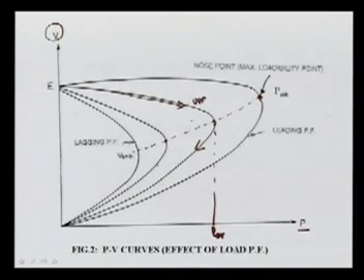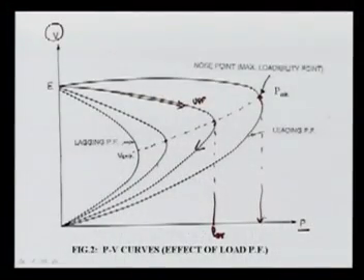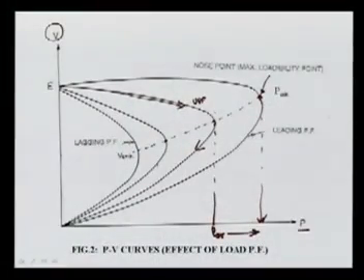Now if your power factor is leading, you can see the critical loading, meaning the maximum load you can get, is more than this. So this shows that if you improve the power factor of your load, you can load your power system without losing stability due to voltage. Because if your power factor is increased, we have increased this much margin, and then you can consume more power.